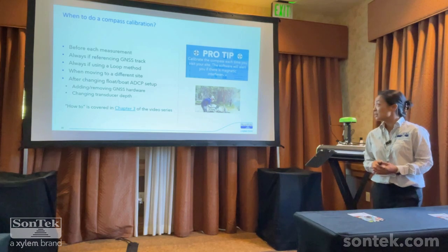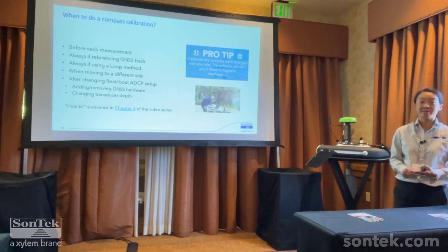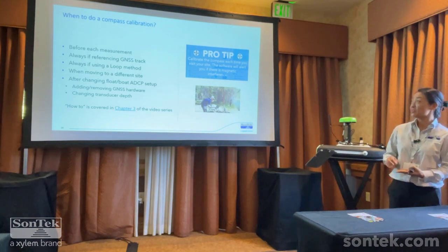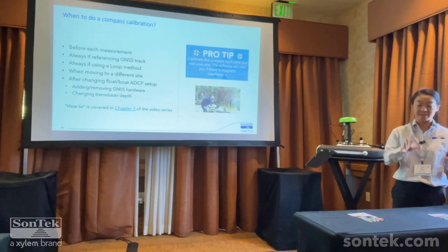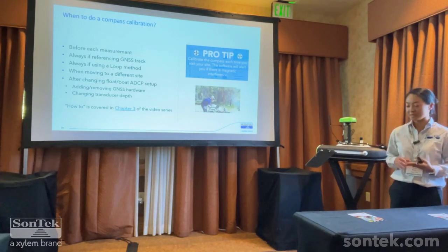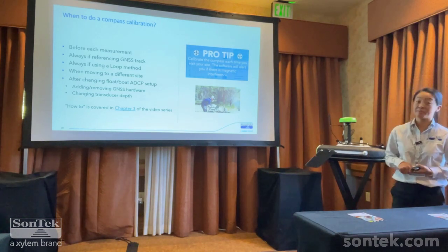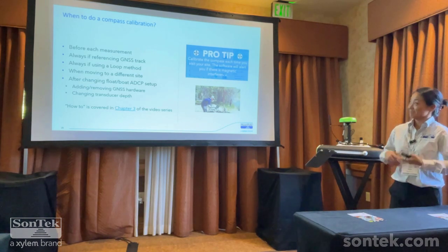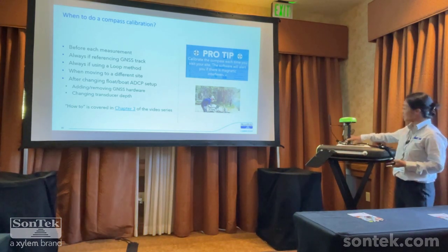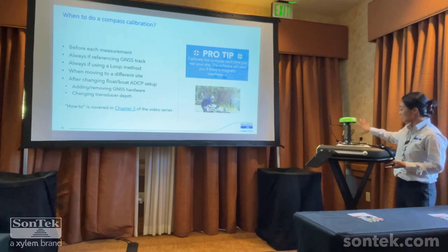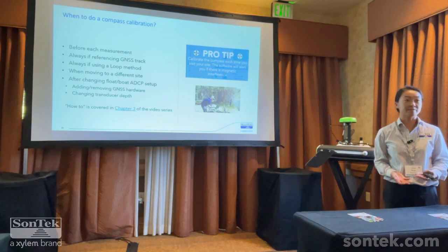So with a magnetic compass, when do we recommend that you do a compass calibration? Generally before each measurement. That's a great idea. You actually do need a valid compass calibration if you are using a GPS track, and I'll explain that in a little bit more detail in a bit. You do need a compass calibration if you're using a loop method moving bed test, and you do need a compass calibration when you're moving to a different site. If you change any configurations on the board, say you change a GPS system, change any of the electronics, batteries, that sort of thing, you generally want to do a new compass calibration.